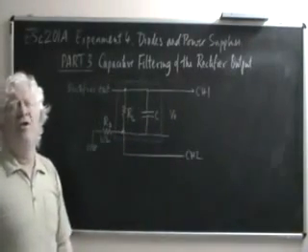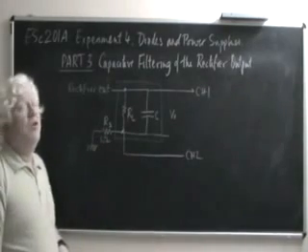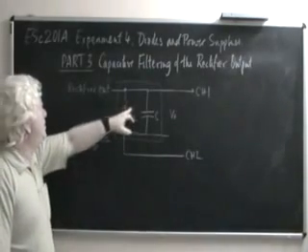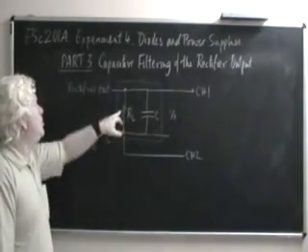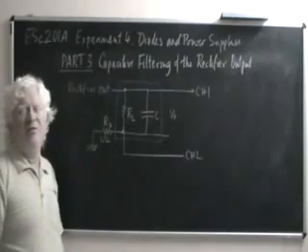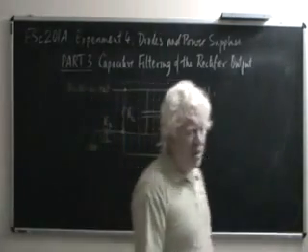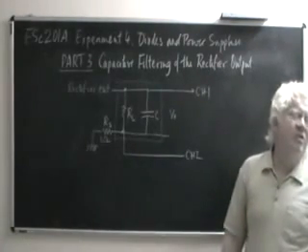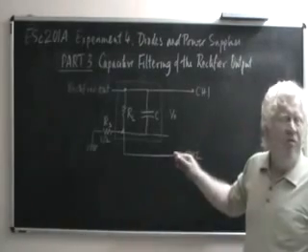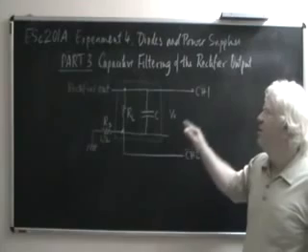We don't require to do it here, because this being a very small resistance, the sum of these voltages would literally be equal to this voltage, because RS is very, very small. Hence, we are going to use the channel 1 output as an approximate measure of the load resistance voltage, or the output voltage of the rectified filtered system.